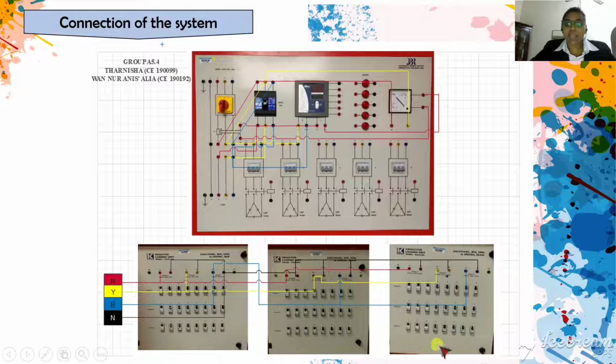And for the power factor correction, when we want to obtain the expected power factor, we will be adding the capacitive loading unit, and same by the parallel connection, we are connecting the red phase from the main going to the resistive, then also going to the inductive, then finally going to the capacitive. And same goes to the yellow phase going to the resistive, inductive, and also capacitive.